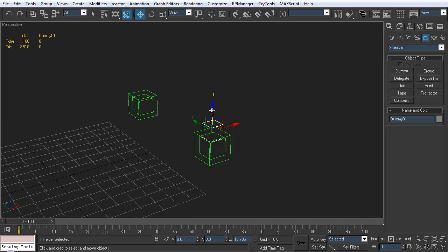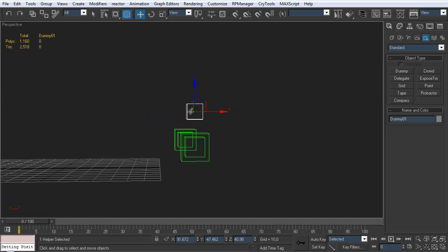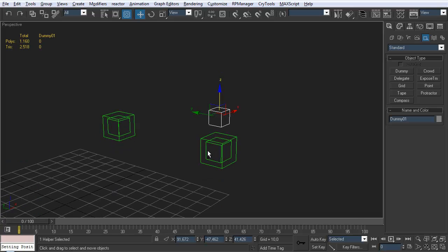Now we will be moving it up. Doesn't matter how much, just an estimate. Something like this. This is actually the point where your suspension will be anchored to the body. We'll call this one dummy susp anchor for suspension anchor, rear left.